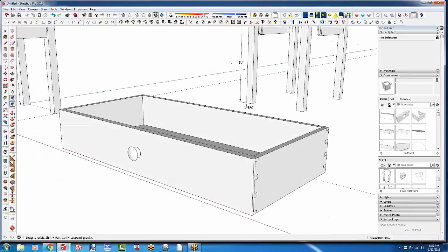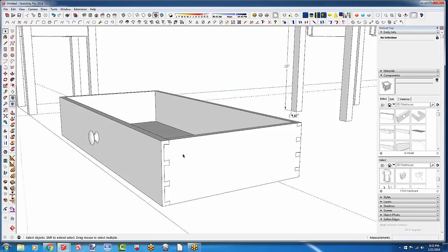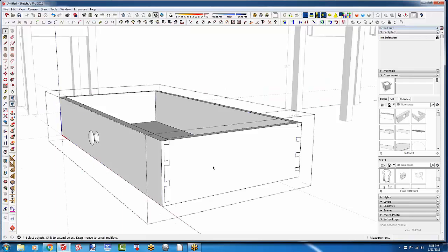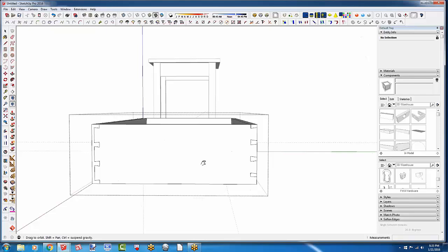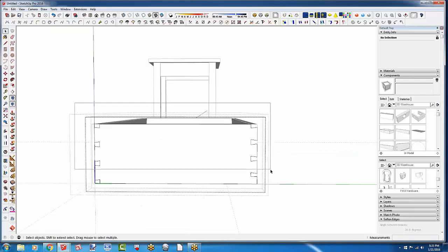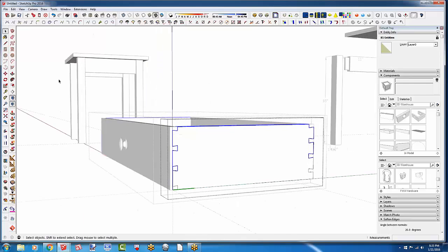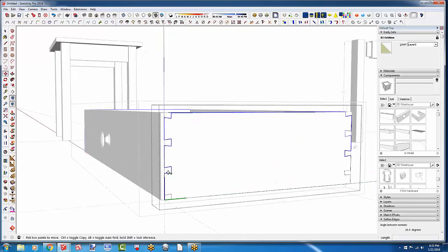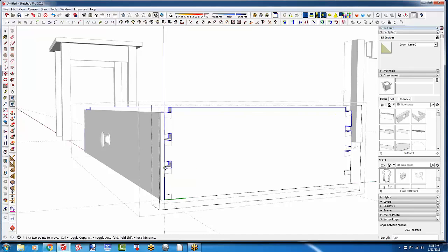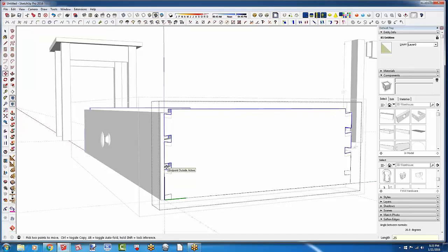The height of a drawer, for example, this one with the dovetails, gets more involved when you've got this joinery, because maybe you want to keep the pins and the sockets the same width, but the tails are going to get to be a different width. You have to make the move in increments. If you want to make the drawer side taller, say 3/4 of an inch taller, well, maybe we would go up 1/4 of an inch.